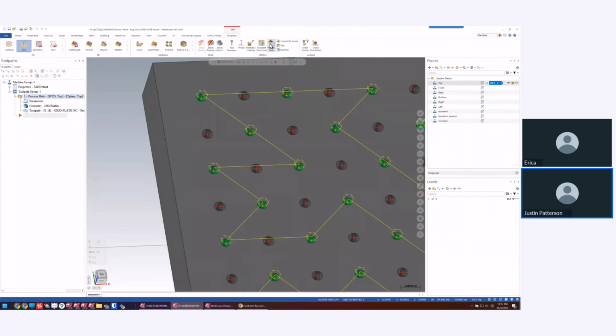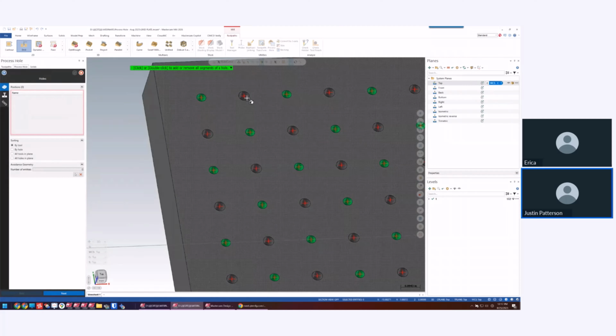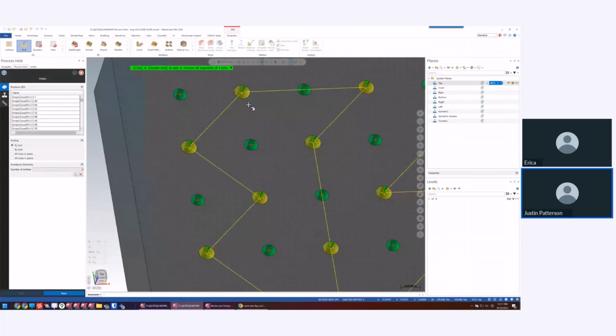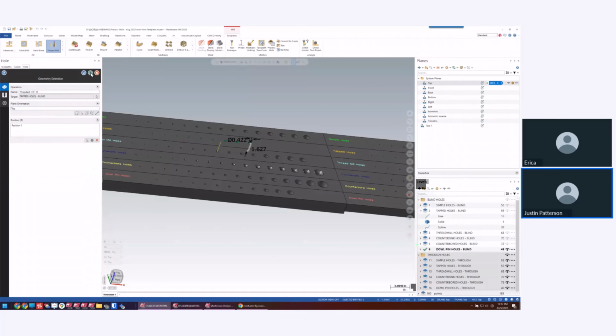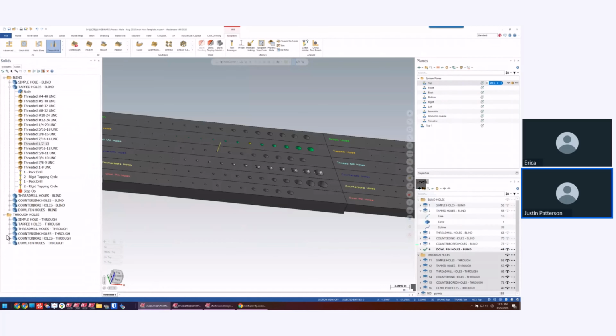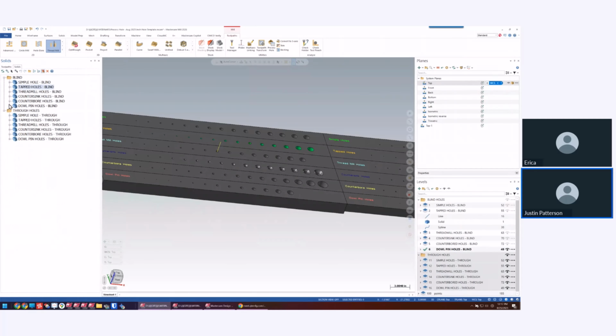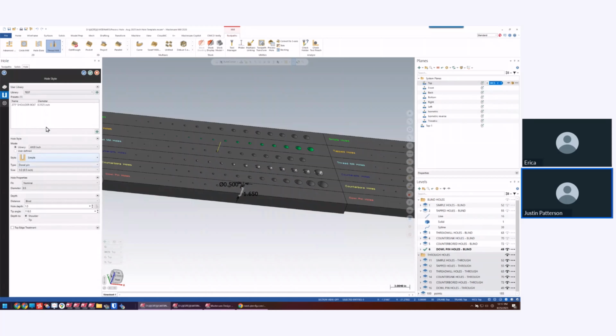I just jump right over here to Process Hole. Control Shift Select. Select these holes. And make sure our dowel pins are correct. Just delete all these. See, like I said, go over here and make sure that what you have it defined as is correct. If you do this a lot, it's really not a big problem. But as you can see, I don't do it enough to even see. I have it as simple dowel, 1/2 inch. That's what everything's driving off of.